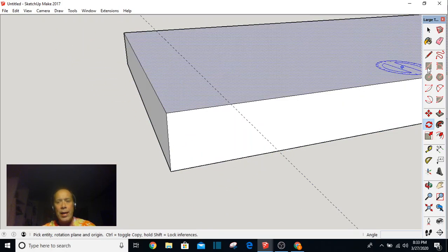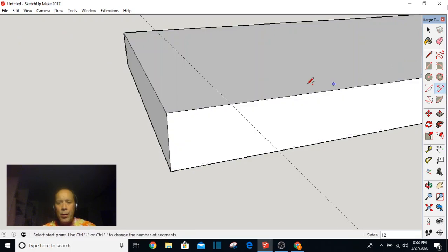So once again, to show you how to do that, grab the 2-point arc, click right there, click right there, make sure that this is that color, which has some sort of light blue. It'll probably tell you, if you watch the video, it'll tell you exactly what color that is, but I'm not red-green color deficient, so I'm not the person here to talk about color. So I'm going to click on that, and I have created a perfect roundover, is what that is called.